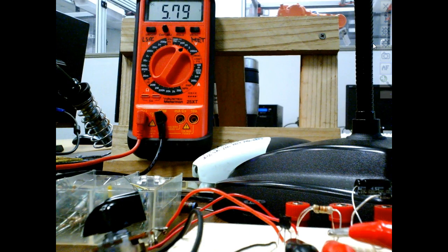What happens to beta when temperature goes down? It goes down. So I've got my car stereo out there, and we don't want the beta to change on our transistor, because that means out there in the summertime my amplifiers would saturate, and then in the wintertime I wouldn't hear hardly any volume at all. So what we're going to look at next is how do we control this? How do we keep the beta of the transistor from changing? We have different ways we can bias that transistor.